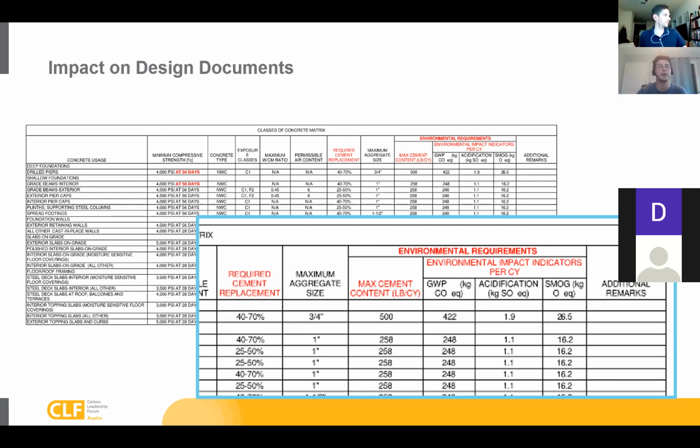And one of the things I'll highlight there is functional equivalence, and having a reasonable baseline. Because when we're doing an LCA, we have a baseline that we're working against. And so it basically has to be, is it the same size, shape, function, environmental performance, or thermal performance, sorry. And is it reasonable? Like I can't compare my building to just a big concrete block. And so understanding that, it is perfectly reasonable to have expected this to be a planar truss, but we went in something else instead in order to get these tonnage reductions. That's why it was effective in the context of the LCA.